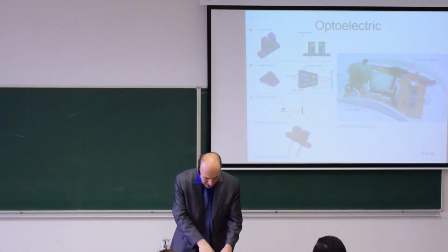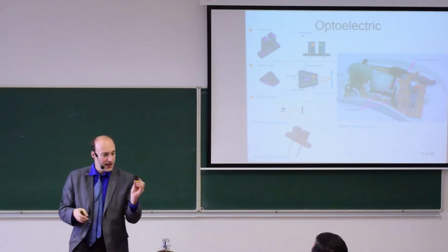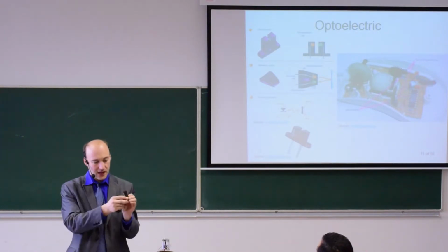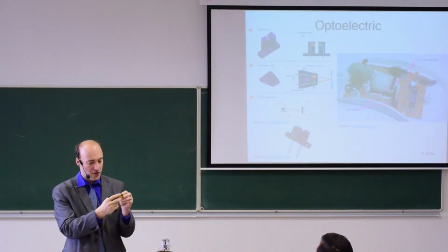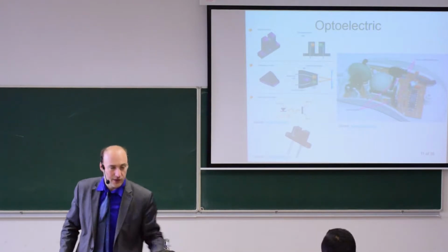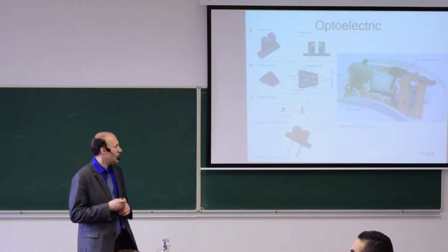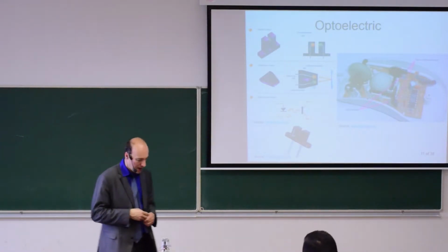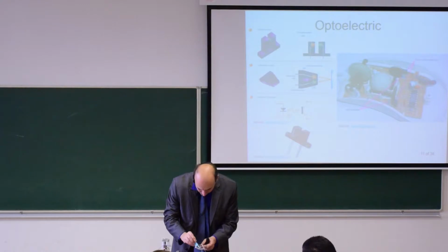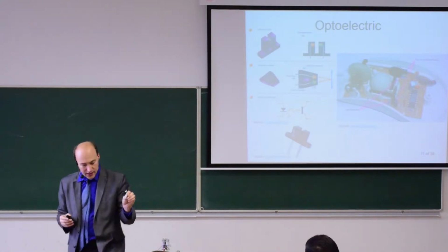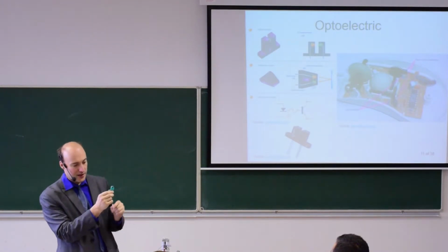Let me see if I have some examples here. Yeah, for example, this is an optical sensor with the slot. One half is the light emitting diode, one half is the infrared phototransistor. It's embedded inside. We cannot see it through it because it's designed for infrared radiation, so it's not for visible light. The reflective sensor, well, no, this is still the version with the slot. So here in the slot there is a disk, and we can pick it up.